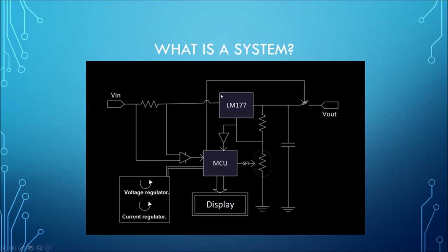LDO regulator, responsible for stabilizing the input voltage. Resistor array. The regulator uses an arrangement of two resistors, one of which is adjustable to obtain an output voltage that is also adjustable. In this case, the adjustable resistor is controlled via SPI serial communication. Calibration system. Since this is a programmable source, the user calibrates both the voltage across the load and the maximum current that will flow through it.